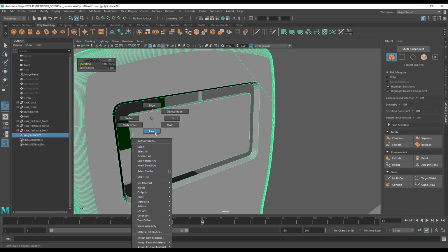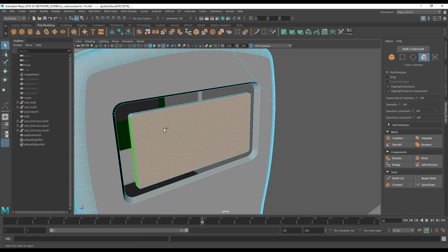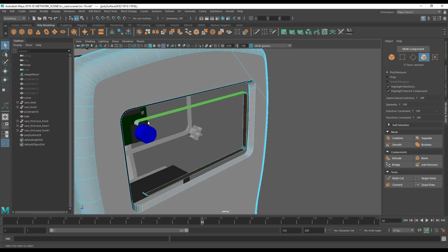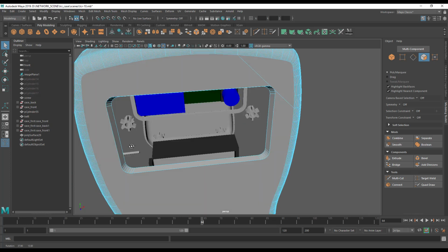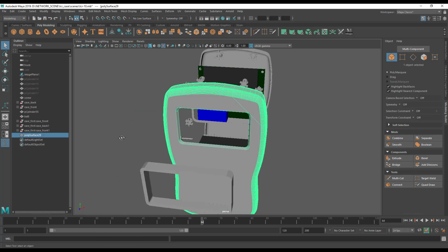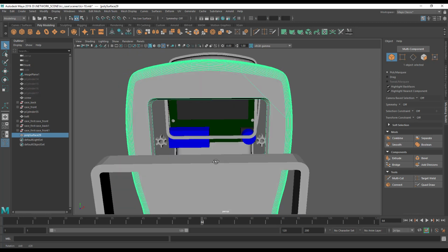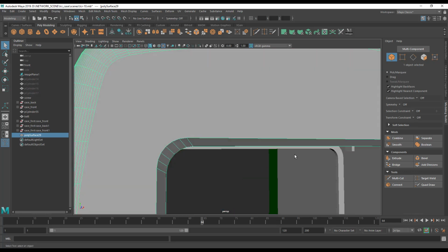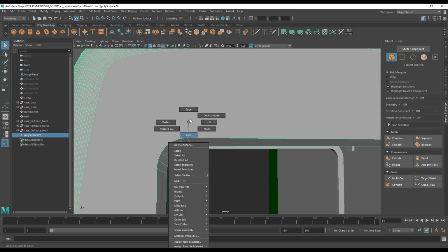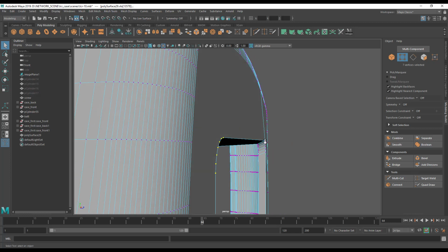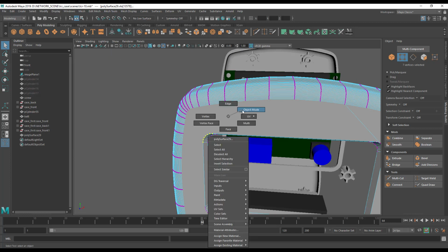Now I've also got this in the way, which is absolutely neither use nor ornament to anyone, but it's very simple just to select the faces here and get rid of it. There we go. So if you need to rebuild a boolean, you can. You can also come in and adjust the size of this by selecting the verts. So if we were to select the verts around here and then scale them or move them, you can adjust the size of this bezel lip around the screen.